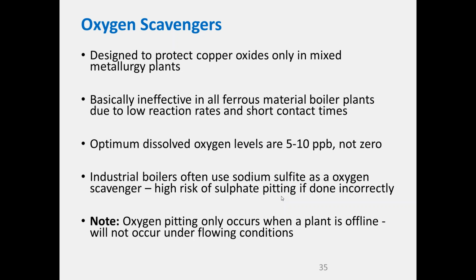Now, you may have heard about pitting and oxygen pitting. Yes, that is a corrosion mechanism that occurs, but what you need to understand is that actually only happens when the plant is shut down. Okay, it's a galvanic type process, and what it needs is a no flow condition. It needs water sitting there stagnant and very, very high levels of oxygen, like approaching saturation, so sort of 9,000 ppb.